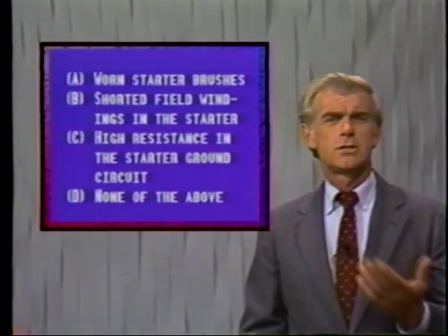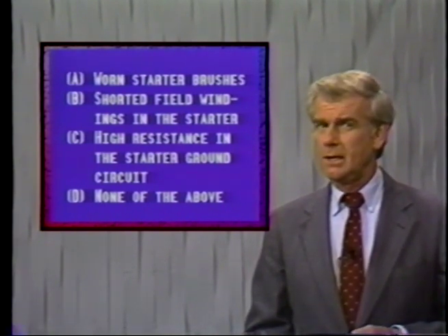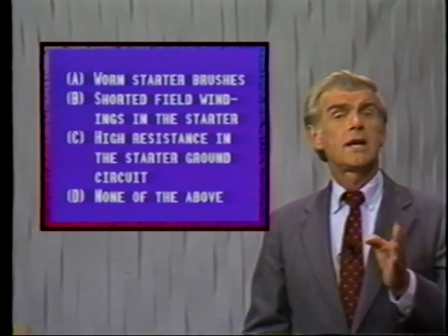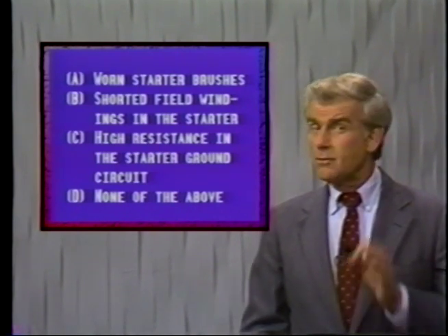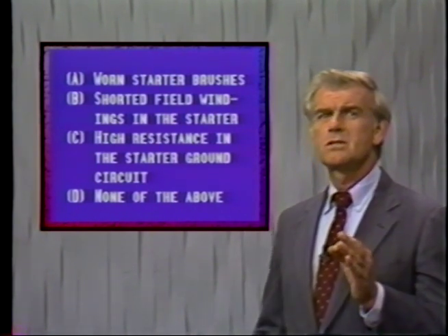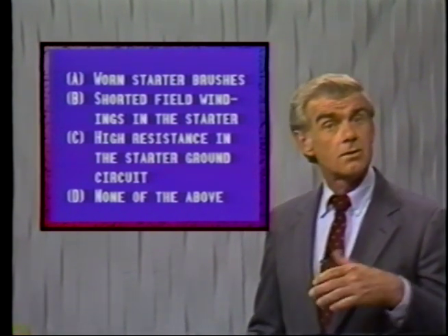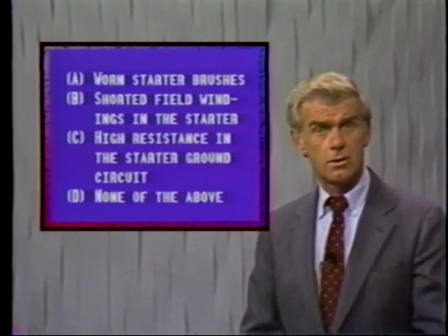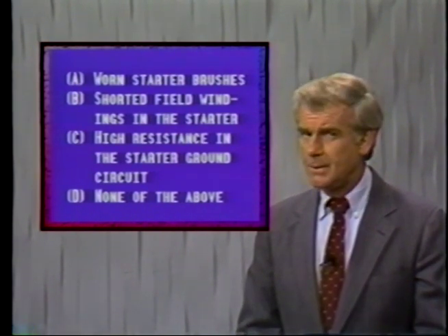This simple choice question is a little more complicated than it first appears, for both technical and grammatical reasons. From a technical standpoint, we must understand the symptom. That is, the starter system cranks slower than normal. This can happen in 4 ways. The first is a low battery state of charge.